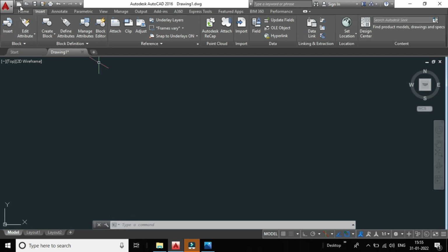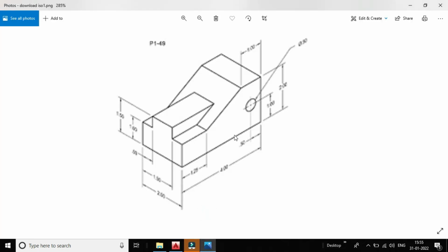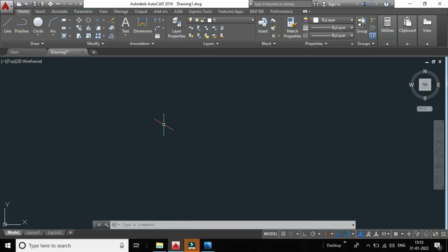Next we will be drawing the model which I have shown you previously here. So this model we are going to draw. For that, let me go to this AutoCAD command and I am selecting line. First I am selecting this point here. Before that I am clicking on the F8 option so that only the ortho mode will be given. So from here to here, let us take it as a 10 mm. Click on enter option here.